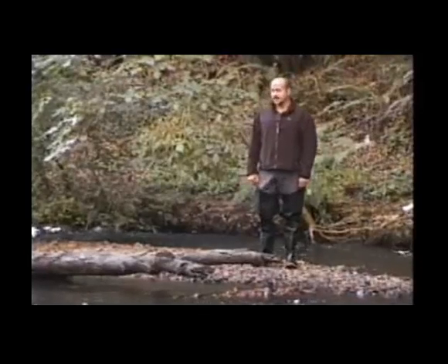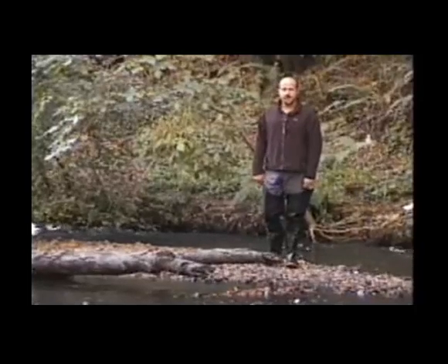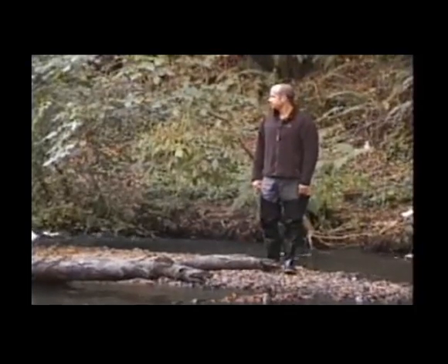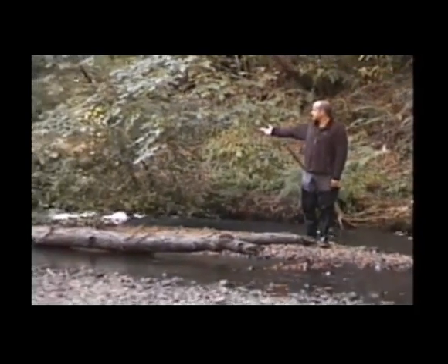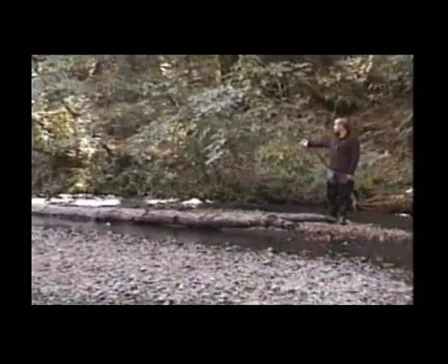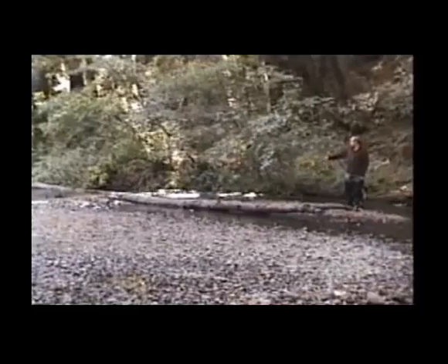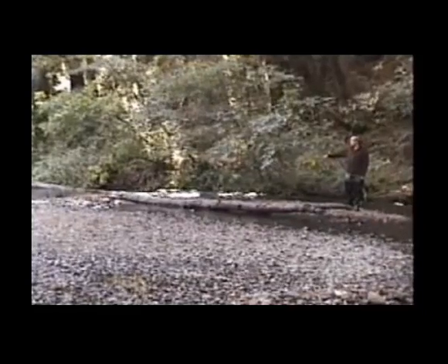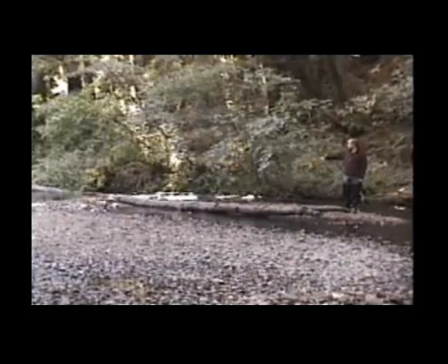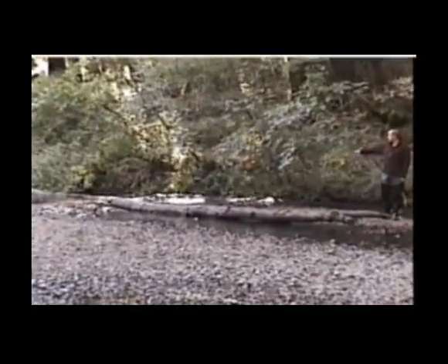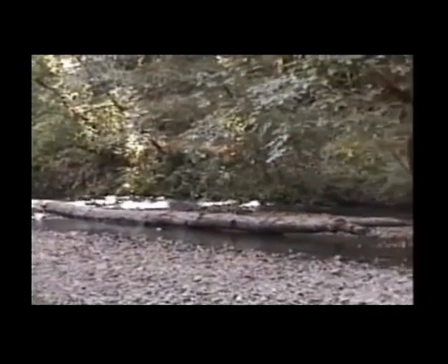Here we have an ideal variety of stream characteristics and different places to sample from. Starting from up here, we have a pool that comes into a mixed riffle with a log jam. Here the stream seems to split with a small island in between, splitting the water that could somewhat mix up the sample. This would probably not be the ideal place to take a water sample. Seeing that we have a variety of characteristics, we'll pan downstream to see what other possibilities we have.